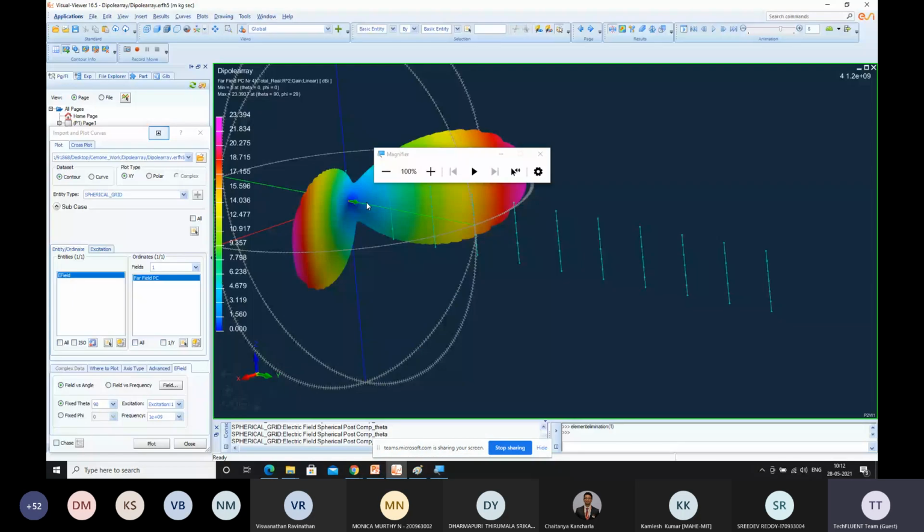So once we are done with the design, we can check with all the excitations. You can see the gain has abruptly improved. Almost it's like 10 times of gain what we are getting. 23 dB, 38 dB. So if you are perfectly resonating at a perfect frequency, at that particular frequency, you'll be getting a very good gain. So those are the observations we have to make.